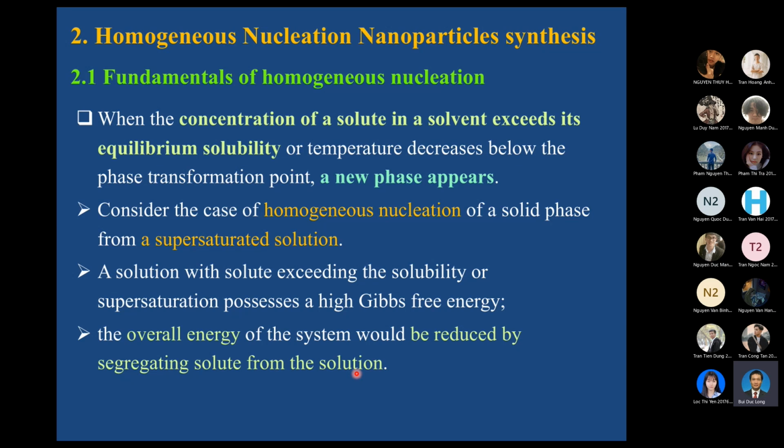And please remember that when the particle size increases, or the surface of particles increases, the surface energy will reduce. So by segregating to form particles, the surface energy will reduce, so the energy of the system will be reduced.